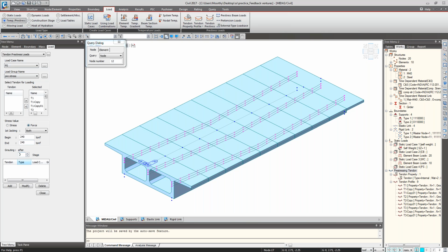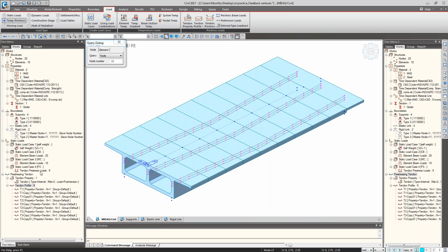And this grouting information is after one stage. This one stage is one construction stage. So that means whenever you are activating the pre-stress, then in the next construction stage, we are applying the grouting details. Close. So now you are seeing the pre-stress load cases display. Now you are seeing the force value in the model.